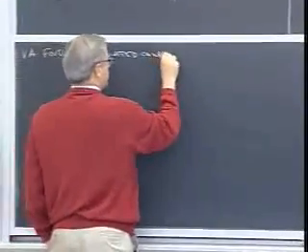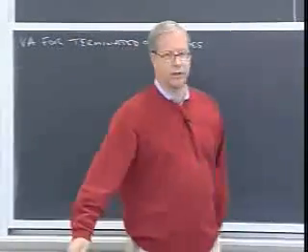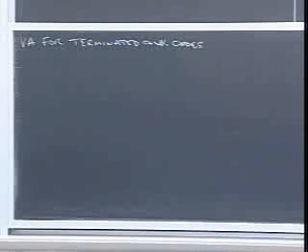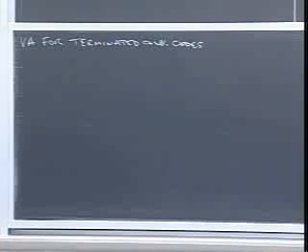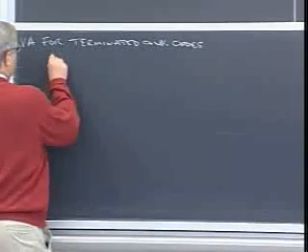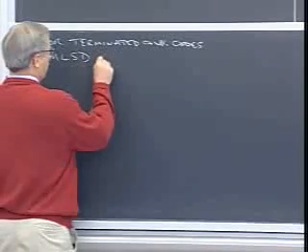I think it's easier first to look at how the algorithm works when you have a finite trellis like this, and then we'll go on and say, well, how would this work if we let the trellis become very long, or in principle infinite? Would the Viterbi algorithm still work? And it becomes obvious that it does. So this is going to be a maximum likelihood sequence detection or decoding algorithm.